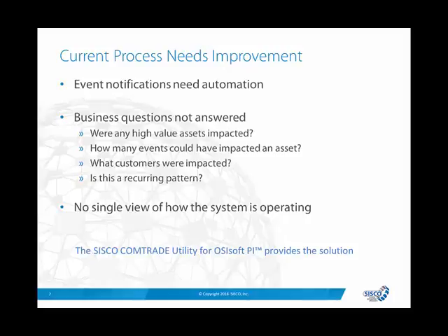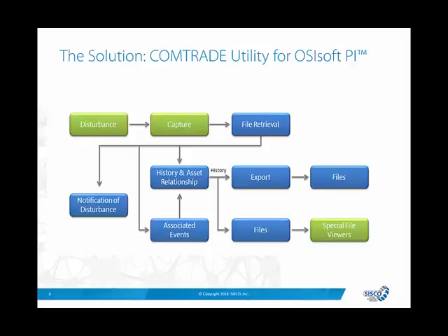How does it do it? Well, the utility actually counts on the proper configuration of triggers to capture the COMTRADE disturbance event in the devices. So the disturbance detection and the capture is actually done in the devices in the field.